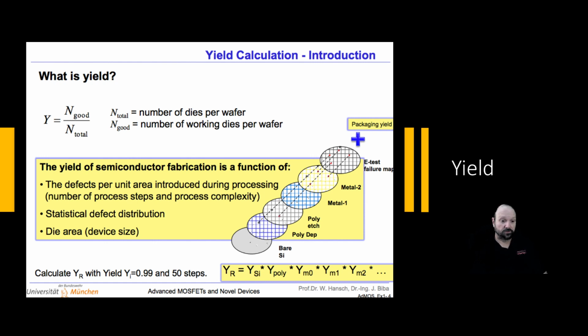What I like about this graphic from the University of Munich, from one of their posted classes, is that it shows each layer of a process for making a semiconductor device. Each layer has a photolithography step, a deposition step, and an etch step, and you build it up layer by layer until you get through making the entire chip.